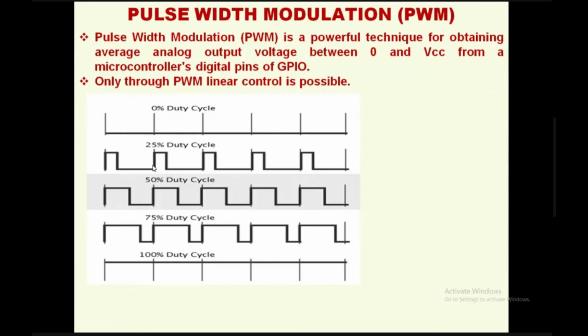சரி, மூணாவது வேவ்ஃபார்ம் பார்த்தா 50% ஆன் 50% ஆஃப், அப்படின்னா 0.5 செகண்ட் ஆன், 0.5 செகண்ட் ஆஃப். இப்படி மோட்டர் ஓடுது. இப்போ நாலாவது வேவ்ஃபார்ம் பார்த்தா 75% ஆஃப் த டைம் இஸ் ஆன். அப்போ 0.75 செகண்ட் ஆன், 0.25 செகண்ட் ஆஃப். இப்படி மோட்டர் சவுண்ட் கேட்கலாம். அஞ்சாவது வேவ்ஃபார்ம்னா மோட்டர் ஓடிட்டே இருக்குது, ஏன்னா ஃபுல்லி ஆன்.